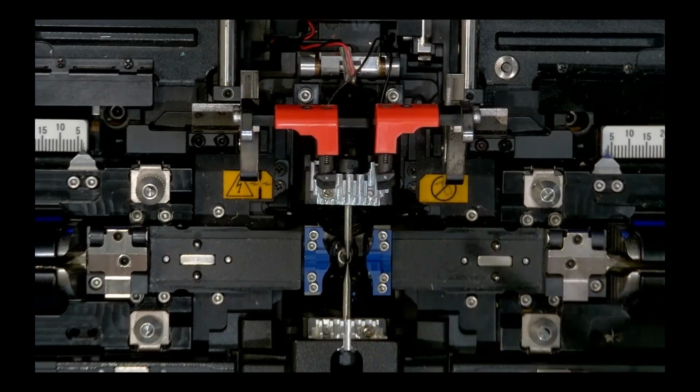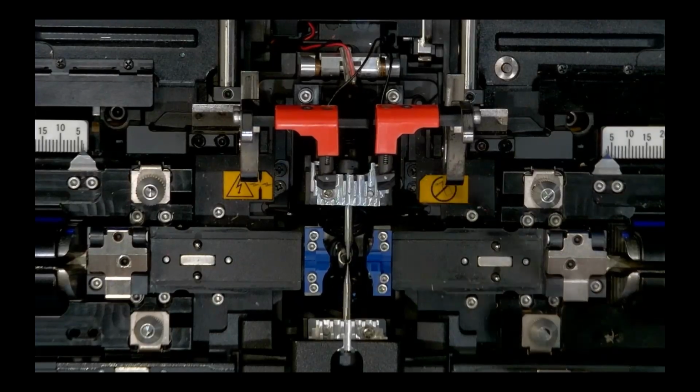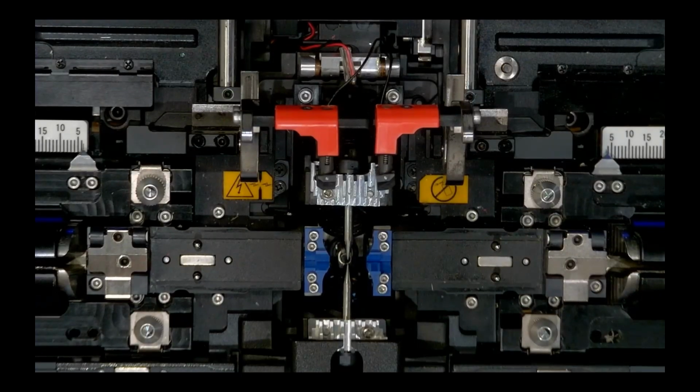Using that method, you can get the actual end view image of a fiber. This is very useful specifically for cases where the fiber is new, it's not known, or there may be some sort of uncertainty in how it should be aligned, or maybe it's too complex for the side view to align it, and so you need to use the end view image to properly align the fiber.